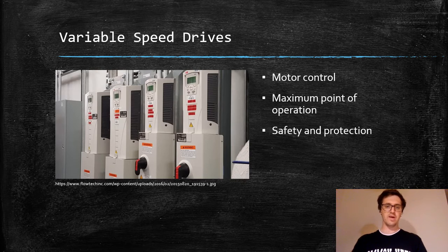Torque limits on the drive prevent fatigue failure of the drivetrain and gearbox, and smooth starts at high torque reduce mechanical stress on the gearbox and reduce roller damage. In summary, variable speed drives provide an elegant electrical solution to help a mechanical system work efficiently.